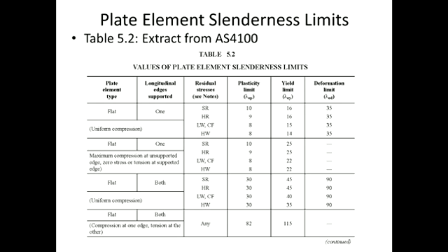So under bending, for an angle section, for you to have zero stress or tension at the supported edge, it would mean that your neutral axis falls on the bottom flange, if you want.